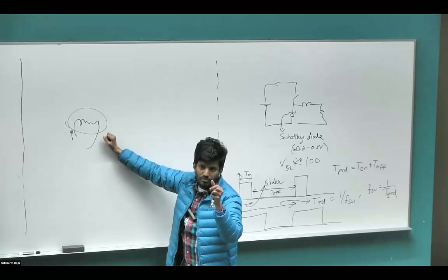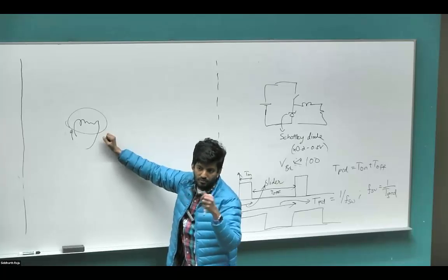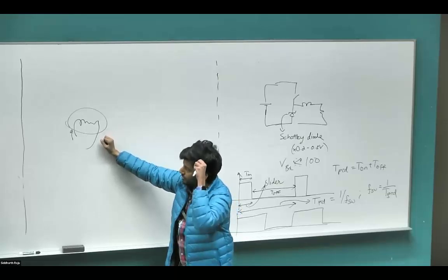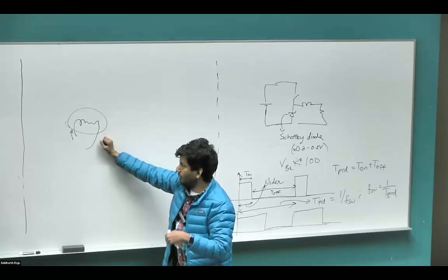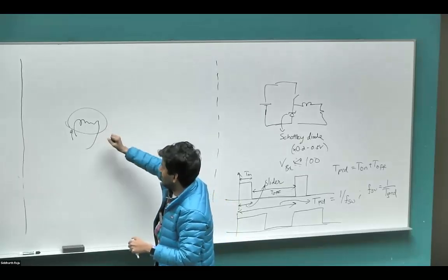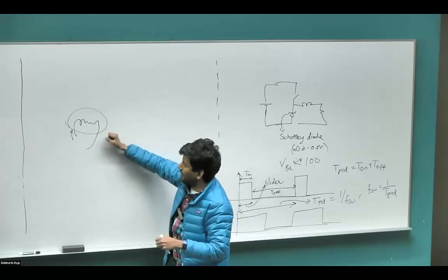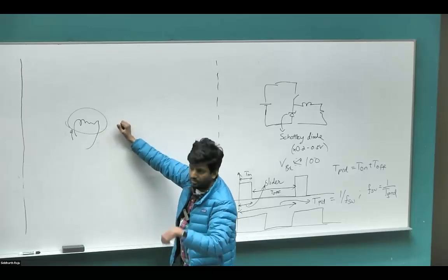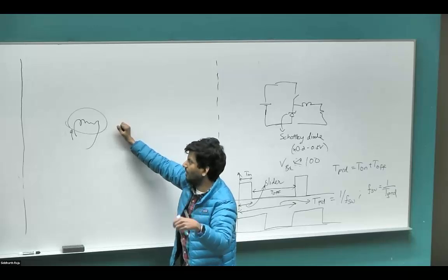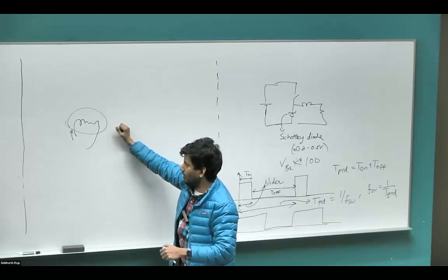There's only 5 to 10% of the energy that's actually used in the visual region of the light spectrum. So it's quite inefficient. That's why we have moved to LED lamps everywhere. But that also means that once it heats up, it takes quite a long time for the temperature to go back to a low enough value that you don't see it anymore, and goes to the infrared region, and then even lower and you completely stop seeing it.